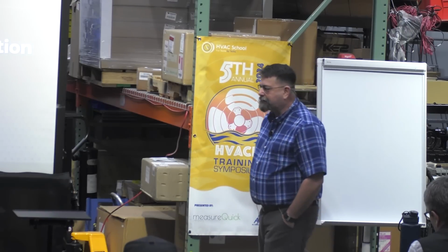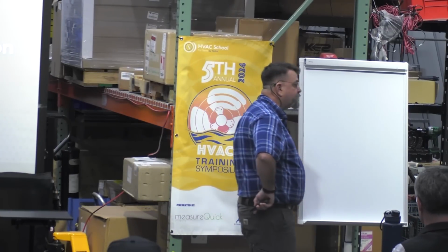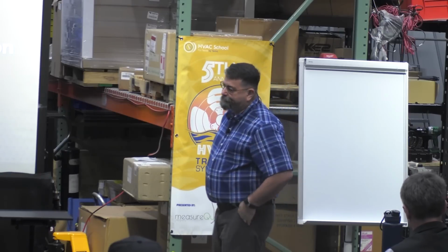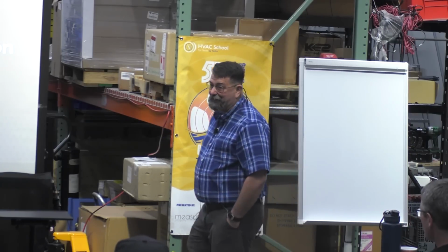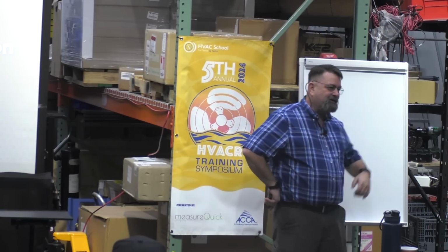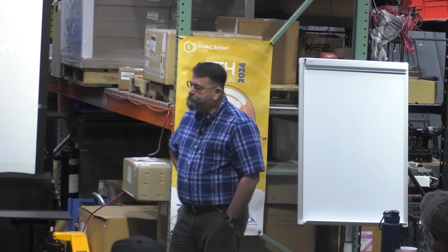Same thing you might do. If we've got a system that's running dry and it's good to go, and we're doing some service work to it, we really want to just be sure we catch carbon. If somebody didn't flow nitrogen, surely they wouldn't do that. Well, somebody takes a Sawzall to a piece of copper, right? Those metal shavings, yeah, they're going to short out 6 compressors. So yeah, I want to be sure to capture any kind of foreign material in there. It's really what it's about.